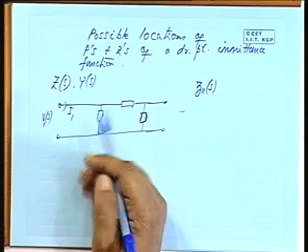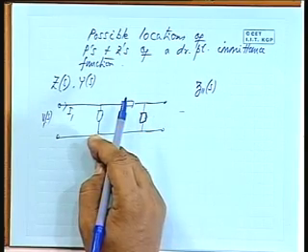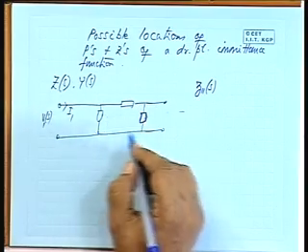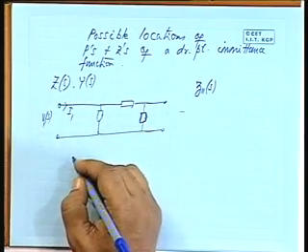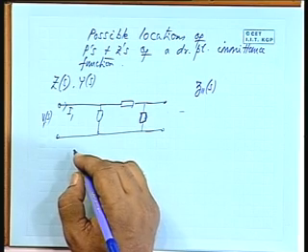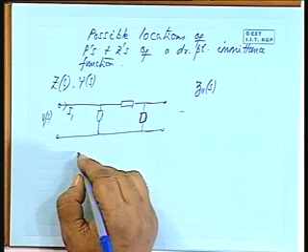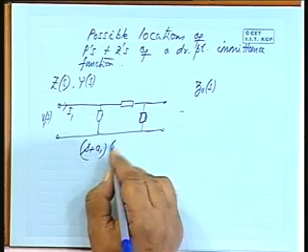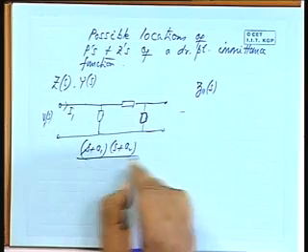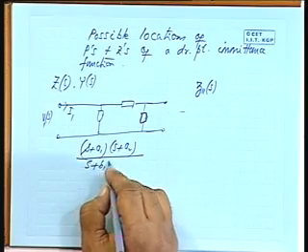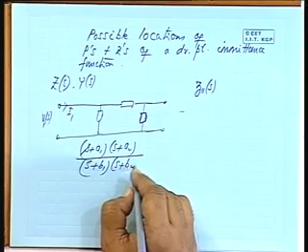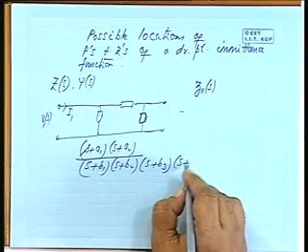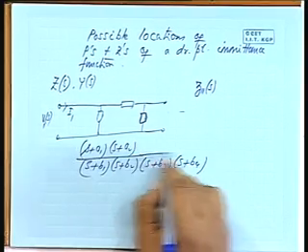We are talking about network elements which are passive in nature, RLC. So, what would be the nature of Z11(s)? Suppose Z11(s) is (s + a1)(s + a2) divided by (s + b1)(s + b2), maybe (s + b3), maybe (s + b4) and so on.